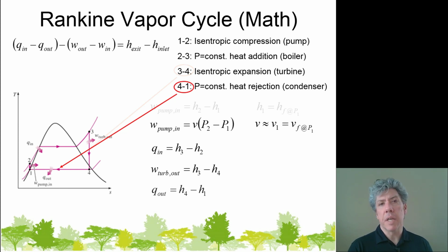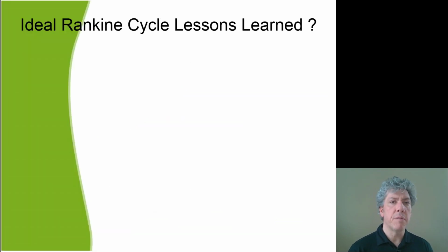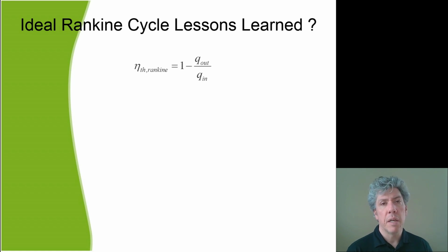So what lessons can we learn from this about efficiency? Well, unfortunately, if we try to play the game we played with the gas power cycles, it doesn't work real well. Instead, what we usually talk about in terms of efficiency of, say, a power plant, which is where this is most commonly encountered, is what's called the heat rate.